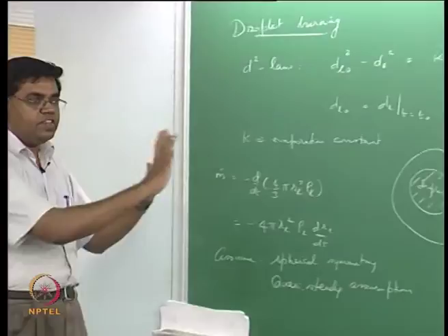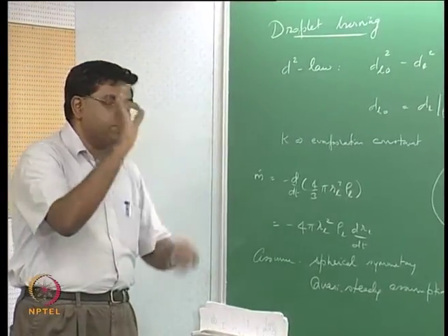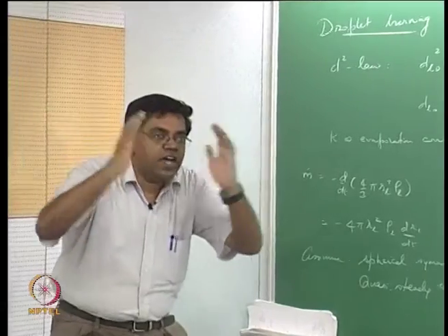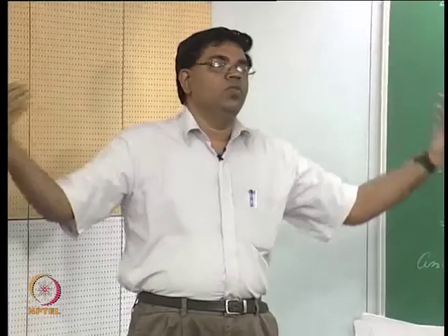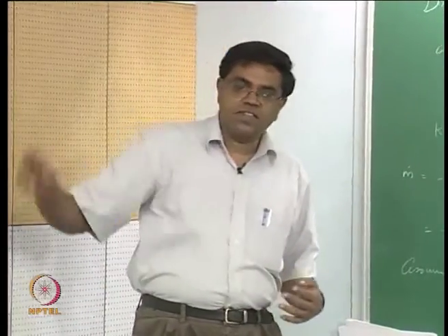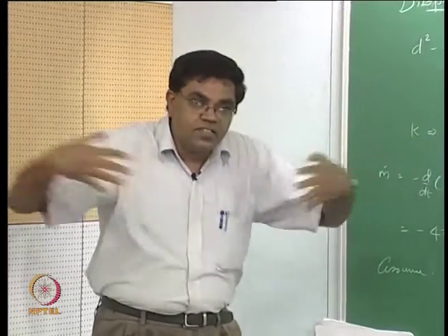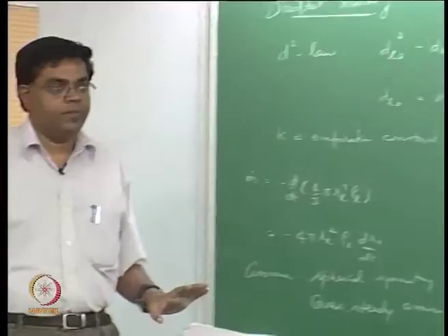That means you freeze-frame your droplet and say, for this particular droplet diameter the gases are instantaneously moving out and diffusing with the oxidizing ambience, forming the stoichiometric surface and hence the flame, and then the heat is instantaneously moving back to this droplet of this particular size.